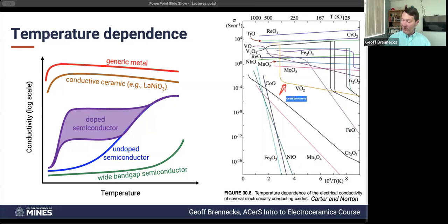These are fun examples. These stair steps are examples of phase transitions. So you actually go through a metal to insulator transition. At low temperatures, it's behaving like an insulator, and then you go through a phase transition and it becomes metallic, and now you've got a lot of free carriers that are available, and from then on it ends up being mobility dominated, and as you continue to increase temperature, the conductivity reduces a little bit because of that reduction in mobility.